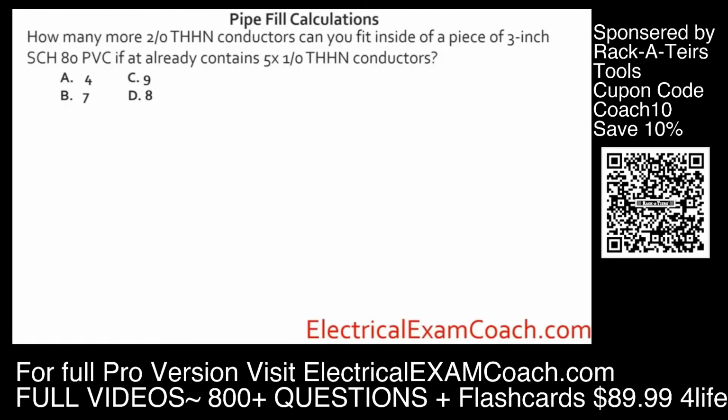How many more 2-aught THHN conductors can you fit inside of a piece of 3-inch Schedule 80 PVC if it already contains 5 1-aught THHN conductors?